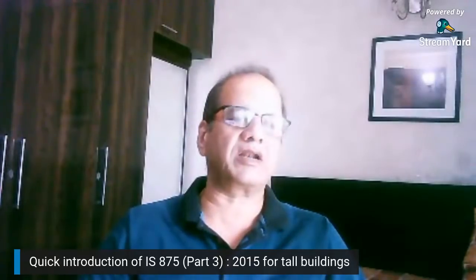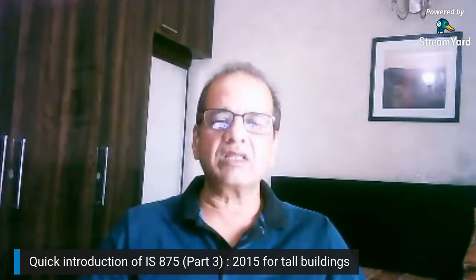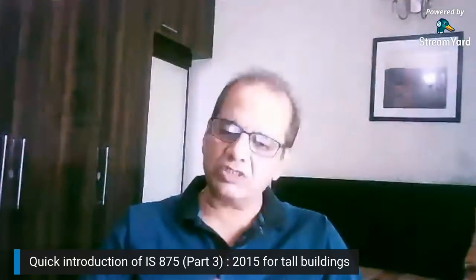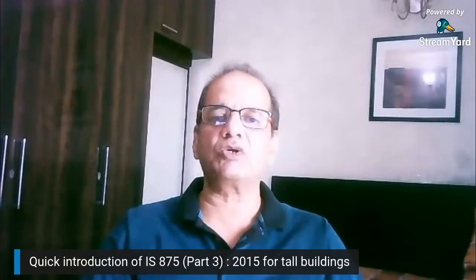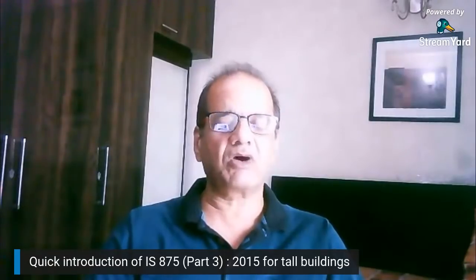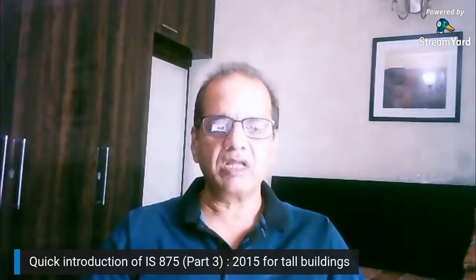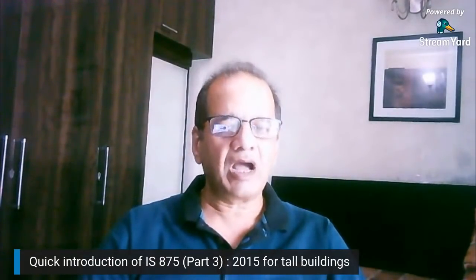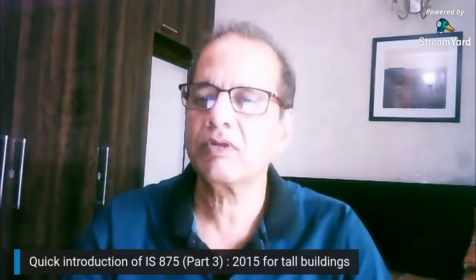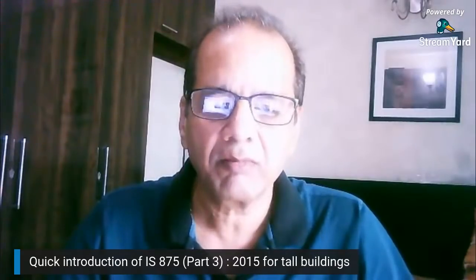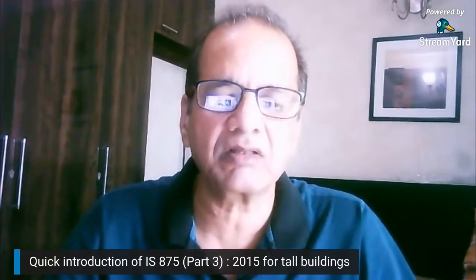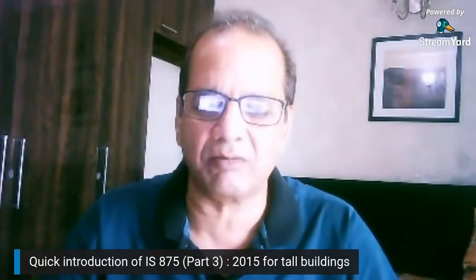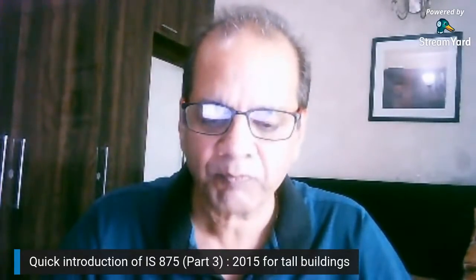The tall building has a shape in plan that is rectangular or square, mostly. There are cylindrical shapes also, and other shapes too, but mostly they are confined to squares and rectangles. So this code is primarily applicable to the prismatic shape. Tall buildings are rectangular or square in shape, primarily, and even circular cylindrical, prismatic. For tapering buildings, we can draw some guidelines from here, but strictly speaking, the flow pattern around a tapering building is a bit different as you move up, as compared to the prismatic rectangular or square building.